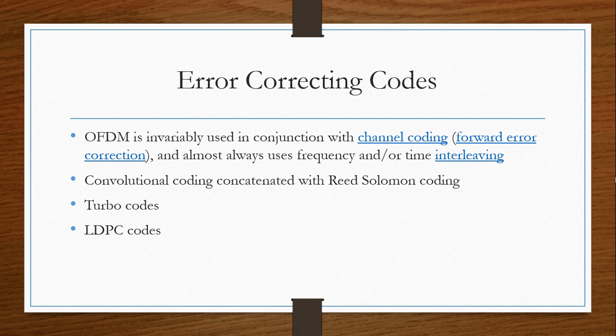I'd like to then talk about the turbo codes and the LDPC codes. The name turbo code arose from the feedback loop used during normal turbo code decoding, which was analogized to the exhaust feedback used for an engine. In information theory, turbo codes are a class of high-performance forward error correction codes developed around 1990 to 1991, which were the first practical codes to closely approach the channel capacity, a theoretical maximum for the code rate at which reliable communication is still possible given a specific noise level.